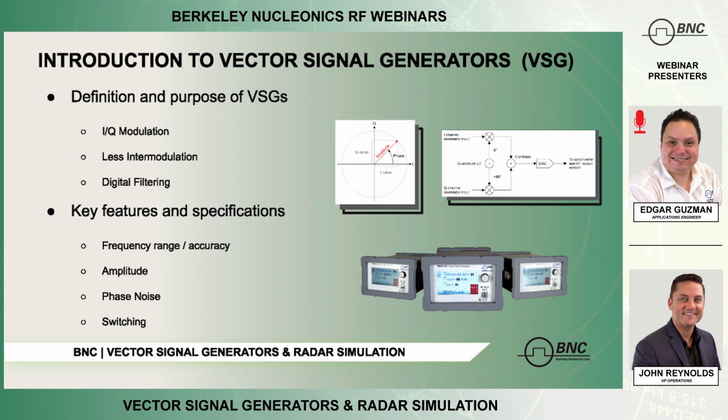So the main feature of the vector signal generators is it can do the IQ modulations. That's how you generate a majority of your signals, and you can mimic or duplicate a lot of different modulations, AM, FM, phase, using IQ modulation. And there's also, with the benefits, less intermodulation, and you can't see it on this actual picture here, but the I and Q signals are coming from digital filtering. So whether that be a band pass or low pass filter, that's filtering out the unneeded frequencies of your signal.